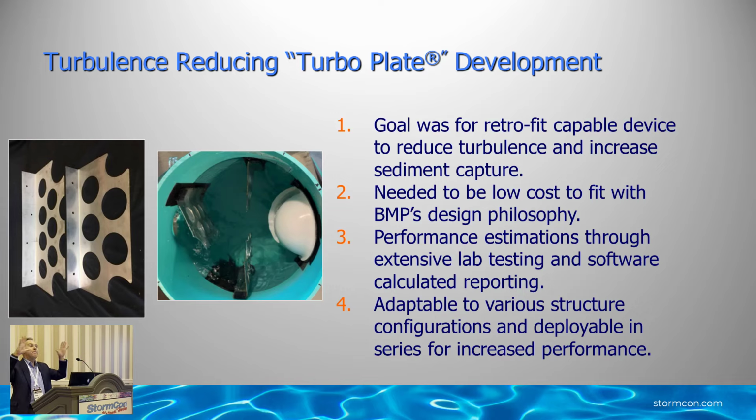Well, that's what happens when you're using these baffles, right? And you're using these holes. The same amount of water is going through there, but now it's intercepting all of that surface area and all of that distance around all of those perforations. Same amount of flow, but the velocity goes down. And then when the velocity goes down, your turbulence goes down.